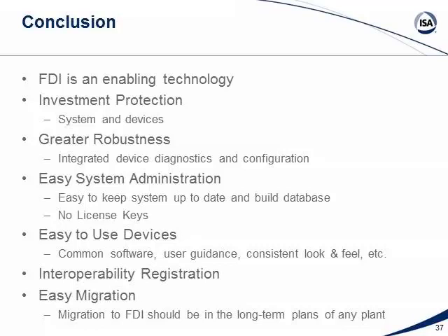How many times when you buy a device and set up a plant, you engineer it, and you say, all right, we're going to use the Rev 1 device. We do all the system engineering, and you go to SAT and FAT. Now I go to the installation, and what shows up in the box? A Rev 3 device. Well, that's not what I engineered to.